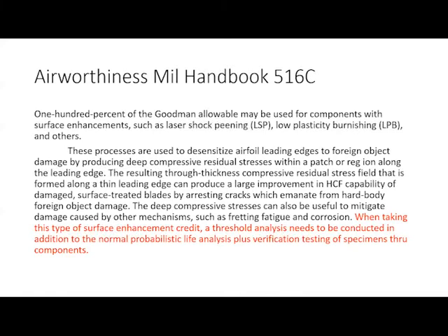Usually it's just specimen based, but here to get 100% Goodman, it does require full components. The good news is we have done it and it's been very successful. So that's kind of where the airworthiness and the design side from the military sits today, and why an enhanced modeling system is required.